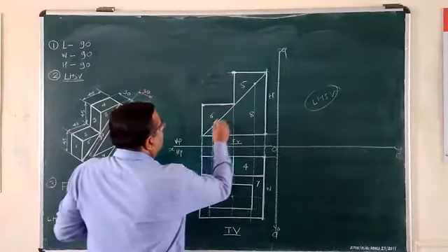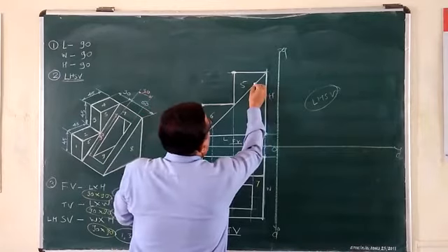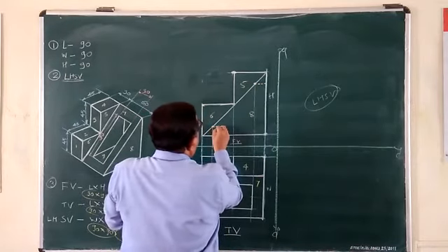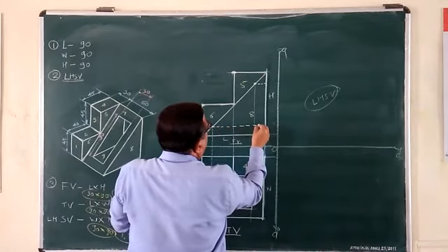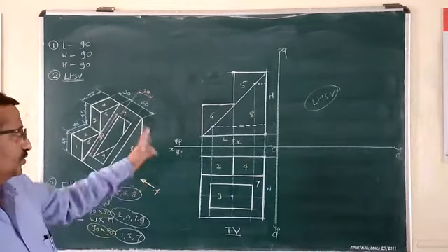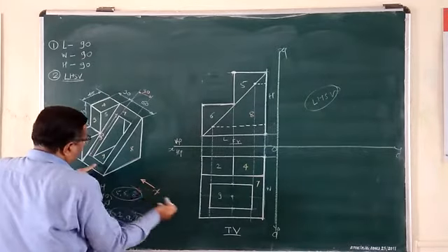So these are the points from where that hole has been cut. So in this way, horizontal dashed and thick lines representing four corners which are created due to that cutting of the rectangular hole one should show. Means this corner and this corner both are getting overlapped in this direction.